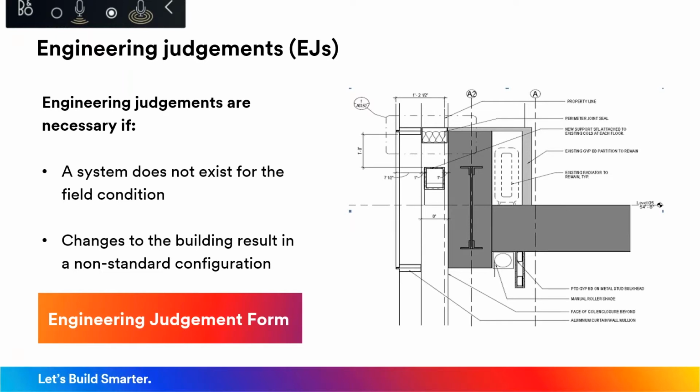You want to make sure that you've consulted with a manufacturer that has test data, that can do some internal testing, that has references and the history to support your installation. So don't guess at what you're doing. Consult the manufacturer of the material that you're installing. Make sure that, first and foremost, you're installing per a tested and listed assembly.